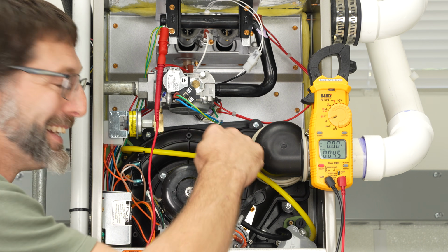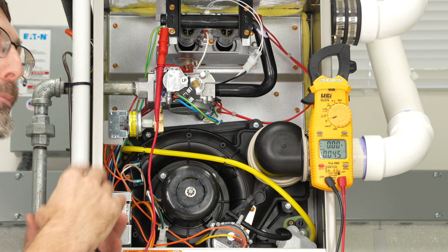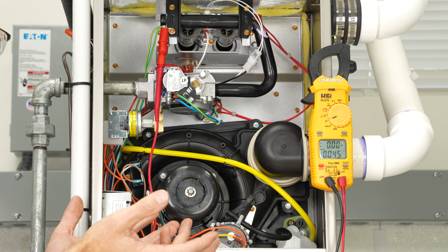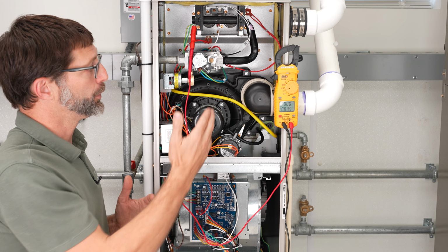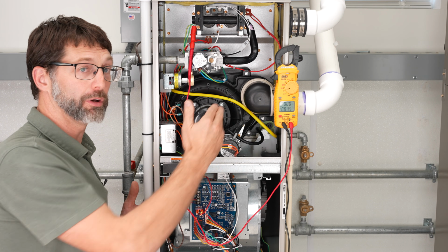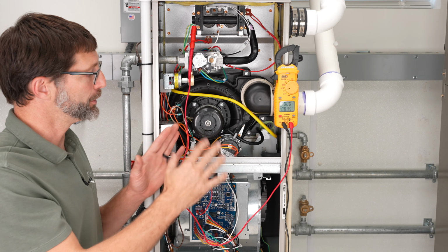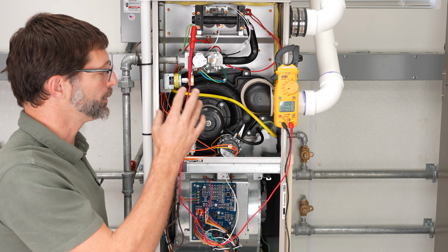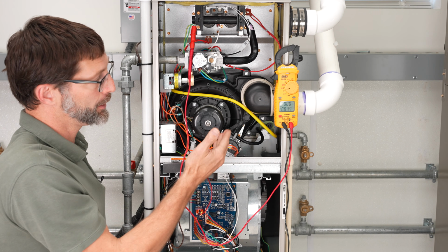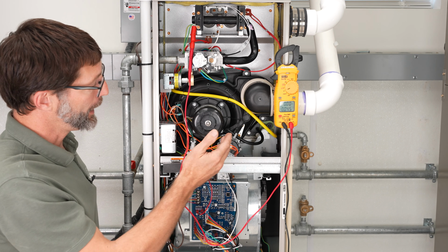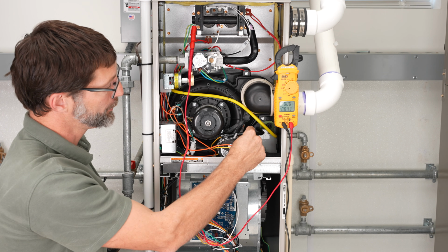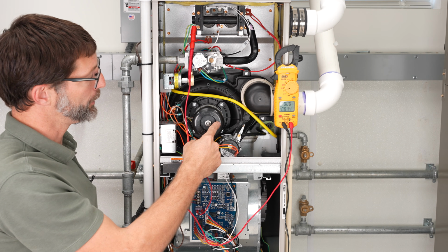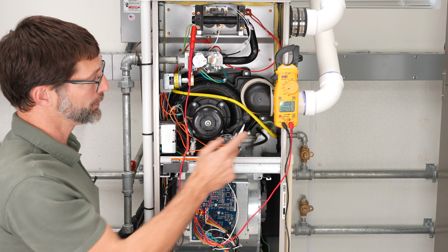The other thing is, on the inside of this inducer motor, there could be some broken blades. Some of the plastic blades may have sheared off. You could have a problem where you have excessive wind blocking the exhaust. There's a lot of things at play in here, and so you want to test each one and visually inspect each one so that you can determine what the problem is. But we're typically starting here with our multimeter, and we're also using a water column manometer, so we can tee in here in order to measure our inducer motor's applied pressure. So let me show you that.